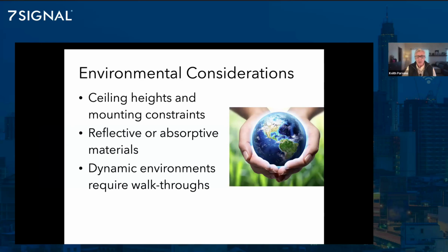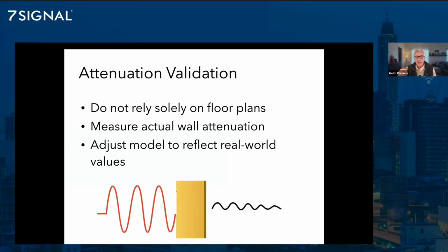And when you go on site, you might want to do some attenuation measurements on a wall. You'll need to take with you something that makes RF, something that measures RF, and then you go on both sides of the wall and you measure the thing that made RF on two sides and see what the difference is. I would strongly recommend the thing that measures RF has the ability to lock on a specific frequency. If I lock on a frequency, I will see all the beacons 10 times per second. I'll get lots of good data points.